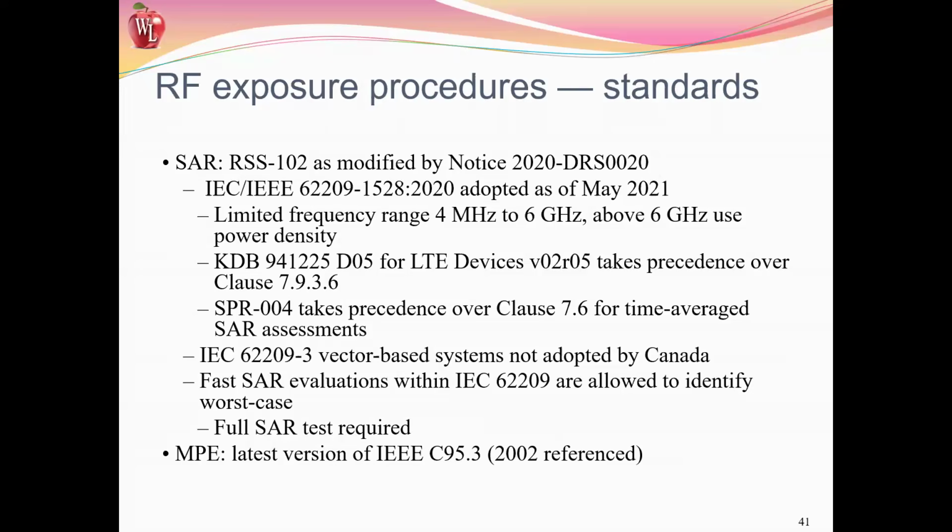There is an IEC 62209-3, which uses vector-based systems, but that standard has not been adopted by Canada or the US. You can do the fast SAR, but it's only to identify worst case. You cannot use the fast SAR to show full compliance with your device. Once you determine the worst case, then full SAR is required on that particular mode.